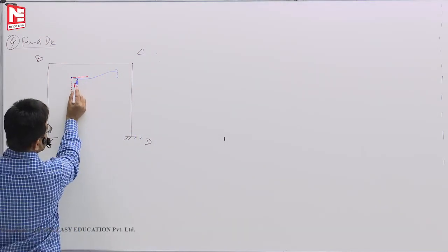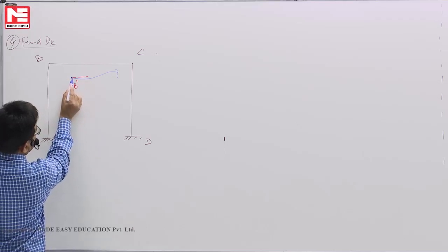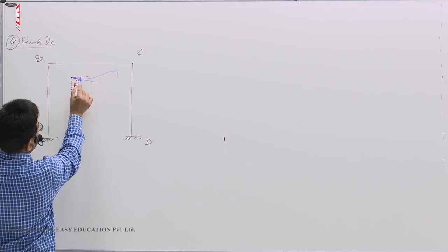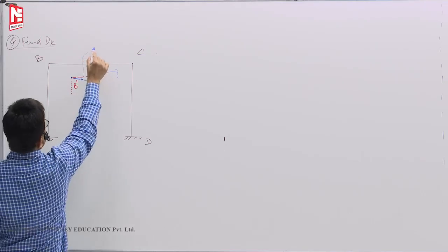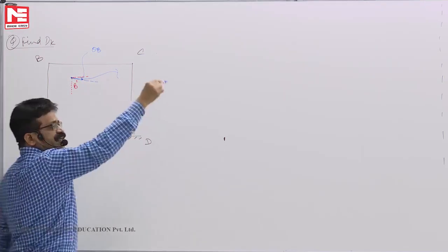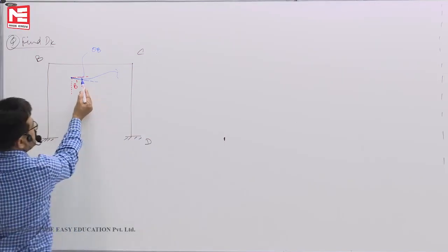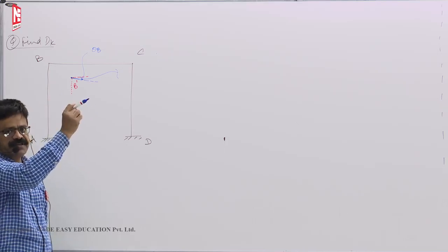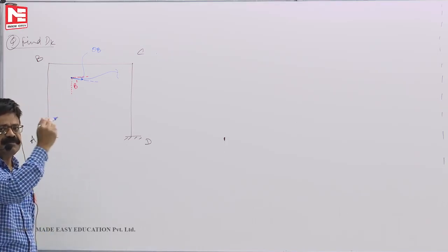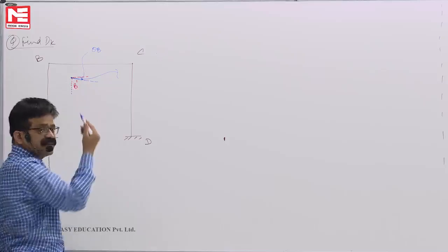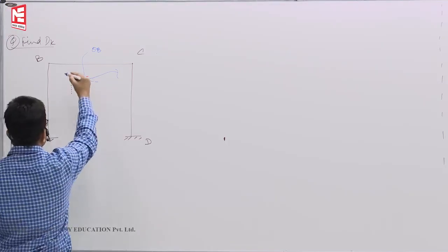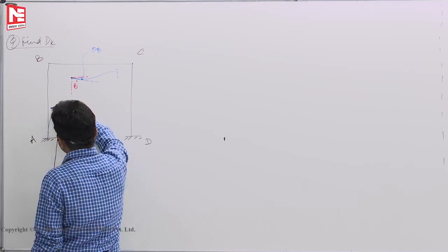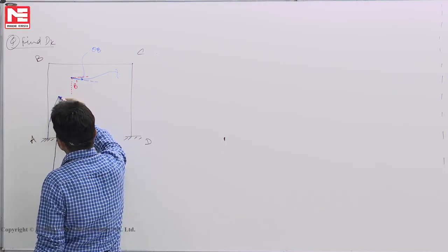Right now we are not interested. You see this is sagging. If you drop a tangent from the initial line, this is clockwise rotation, this is theta B, and the deflection profile is sagging. If it sags when there is no external movement at a joint, if one member sags, another member also must sag, otherwise that 90-degree angle you cannot maintain. So here it should sag, and the deflection profile will go something like this.